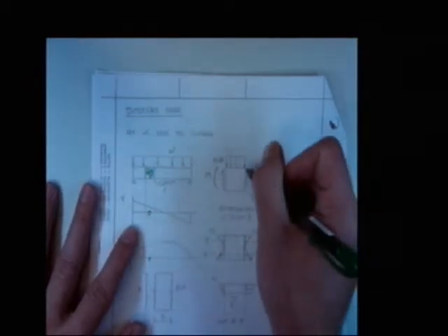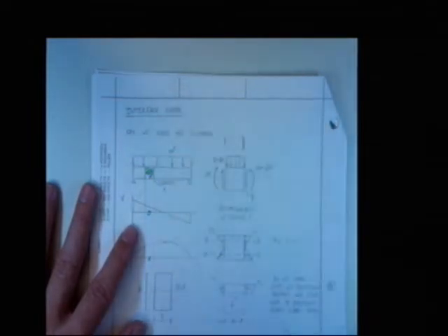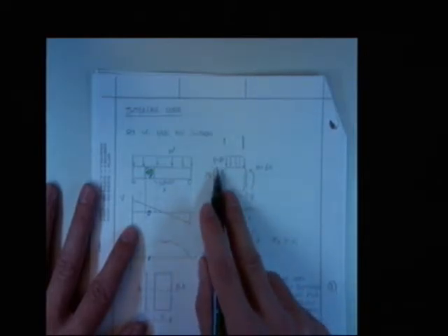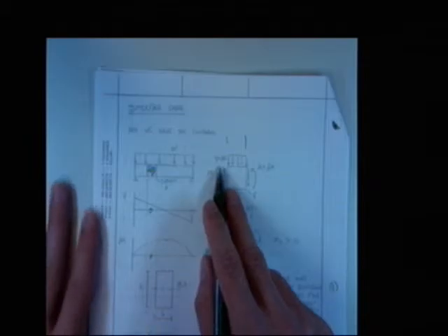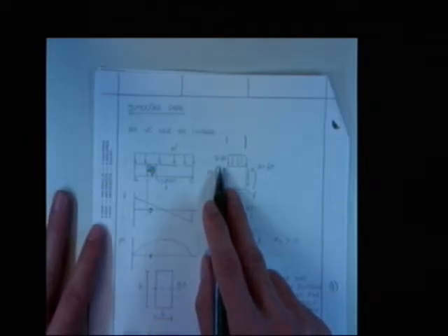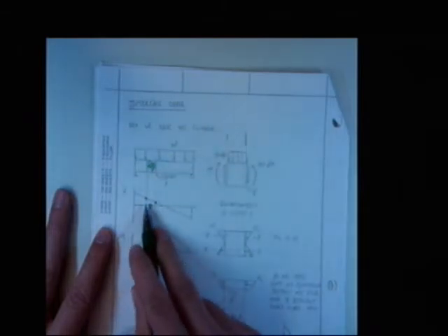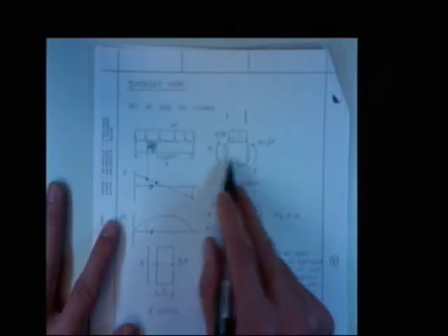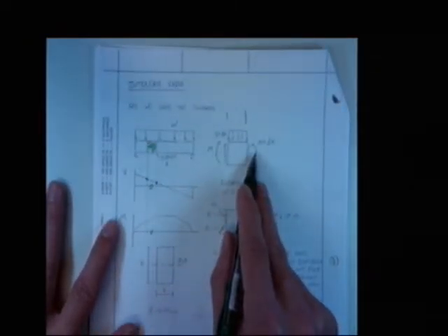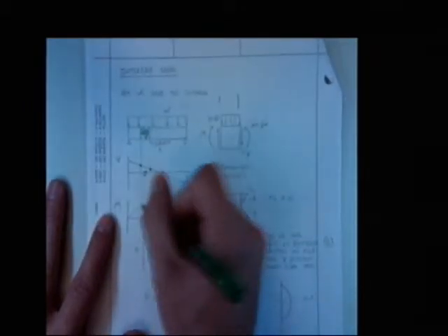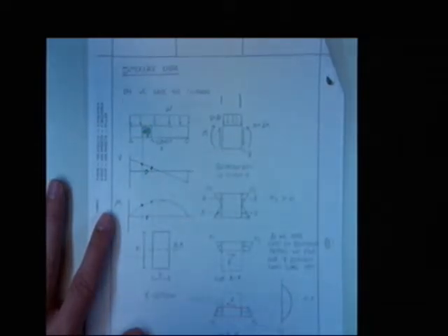And believe it or not, if I compare the right-hand side to the left, this is real important. If I compare the right-hand side to the left, I actually have more shear on the left side. Why? Well, that's what the shear diagram told me, didn't it? I'm comparing this to this. There's more shear on the left-hand side. And if I compare the left-hand moment to the right-hand moment, I actually have more moment on the right side. Does everyone see that? That's just comparing this point to this point. Same thing.